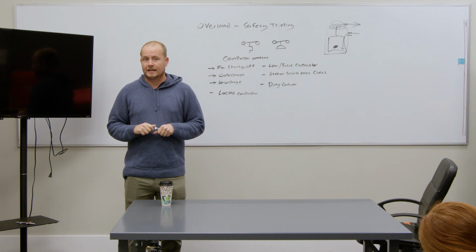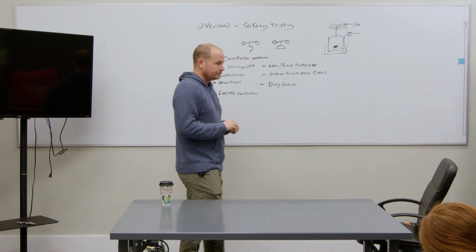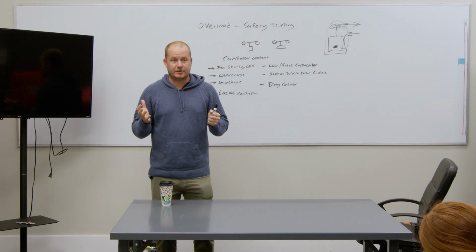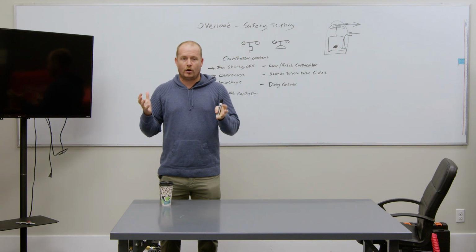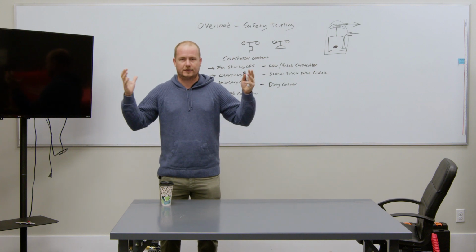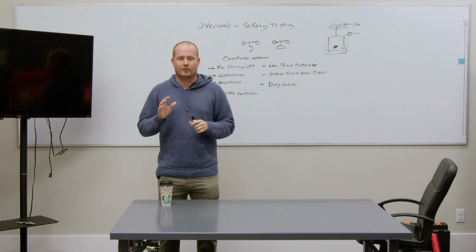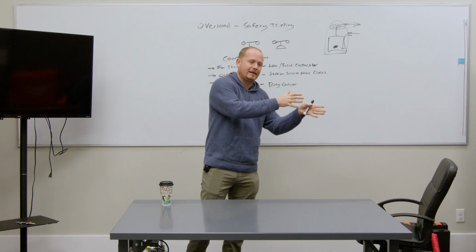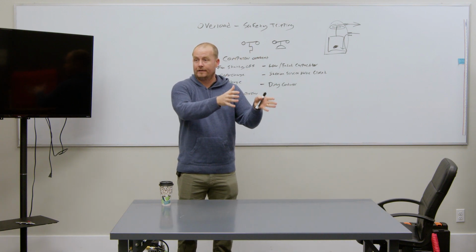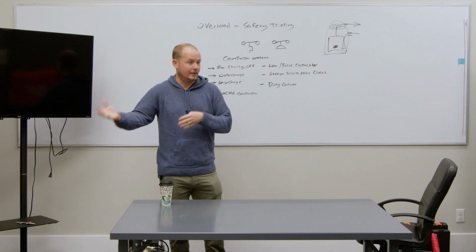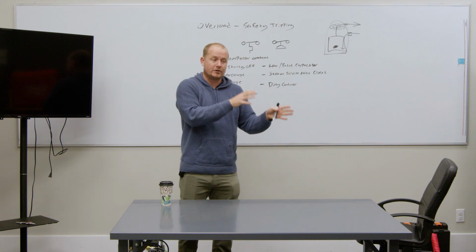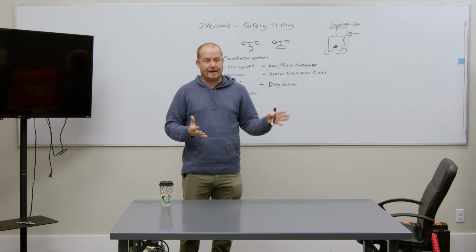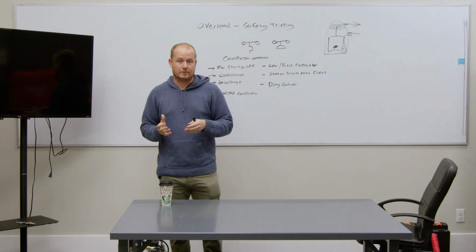Make sense? I think an easy way to think of it is, think of your engine on your car. Your engine could overheat because something is broken in the engine, and that engine is having to work too hard because there's issues with the piston, cylinders, crank, anything mechanical. And then you could have a problem with your engine overheating because of the coolant system, because you're not circulating enough coolant through. You could be low on coolant, whatever. And so think of refrigerant in this case as your coolant system for your compressor. And then you have all of the mechanicals inside the compressor that can also result in overheating.